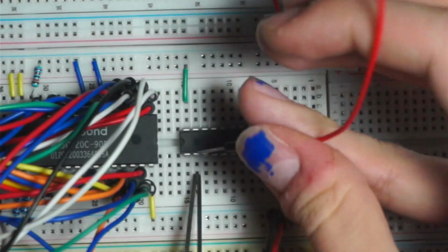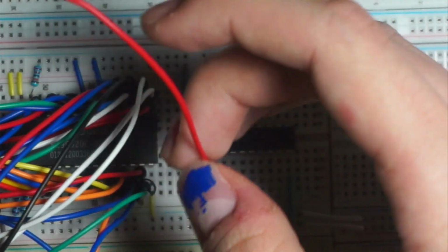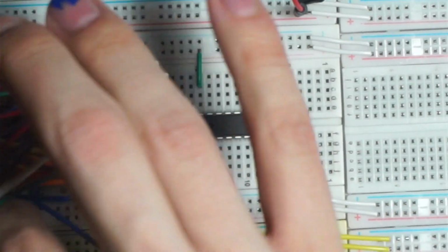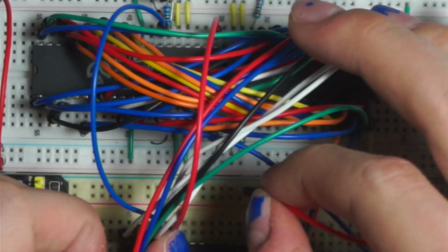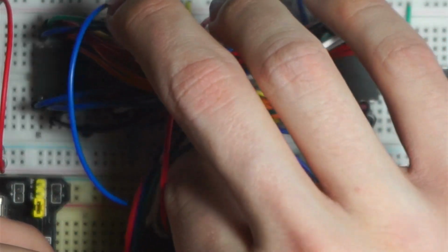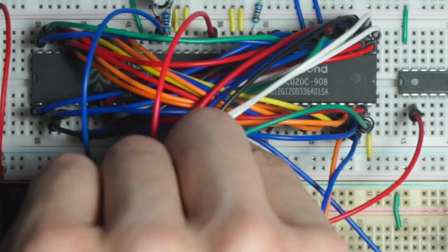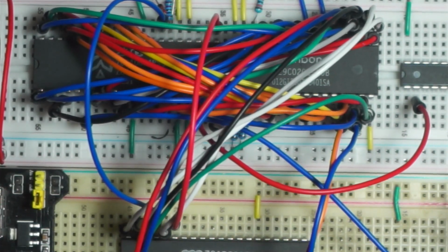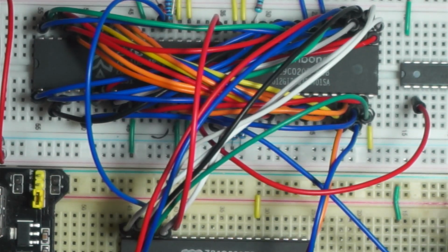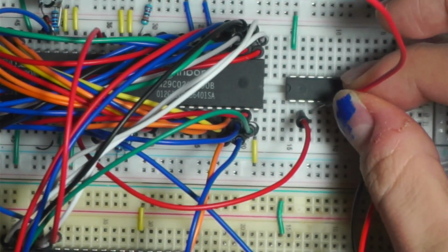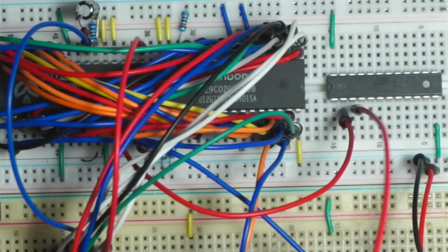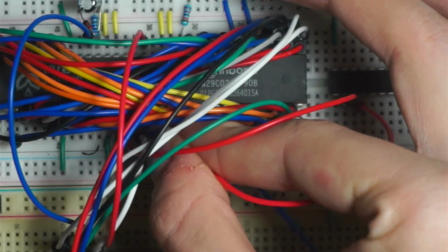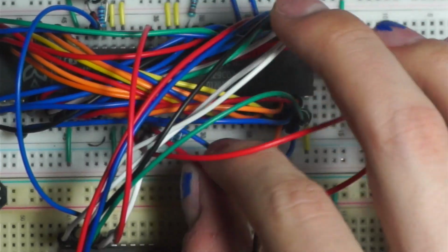So I will connect a wire to the memory request of the CPU, and the memory request is right next to the IO request on the CPU. Memory request. Now the IO request is on the CPU under memory request. This one. And IO request we have already connected to the PIO, so it is at the bottom of the CPU.